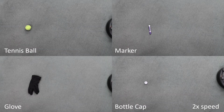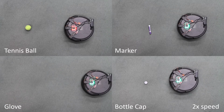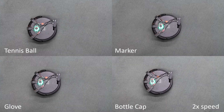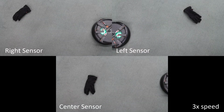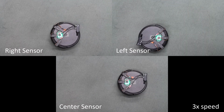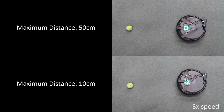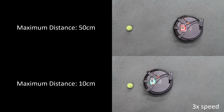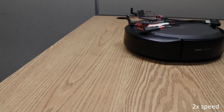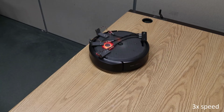The robot is able to detect many types of obstacles, including those which lie much lower than the sensor itself on the robot. The robot can also detect obstacles in any sensor's field of view. By changing the distance cutoff in the raw time-of-flight data at inference time, we can adjust the maximum distance at which the robot can detect an obstacle. Our method can in principle detect any deviation from a planar surface, including cliffs. Again, the maximum detection distance is configurable.